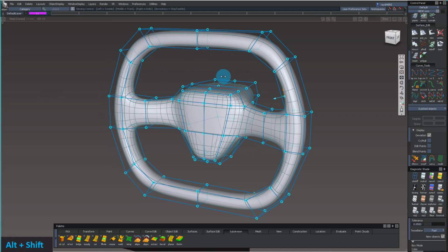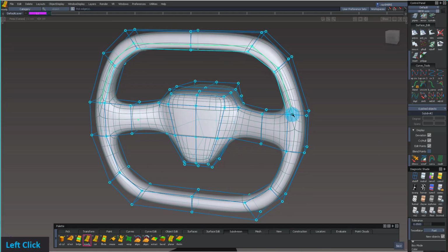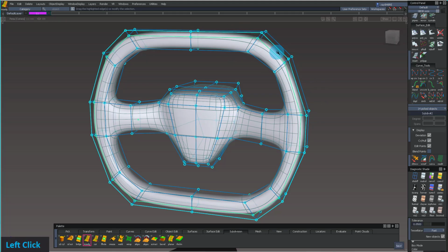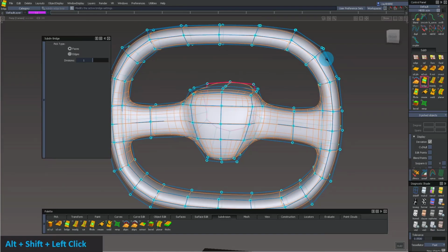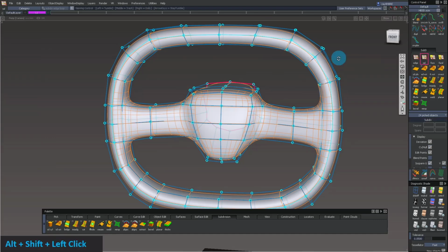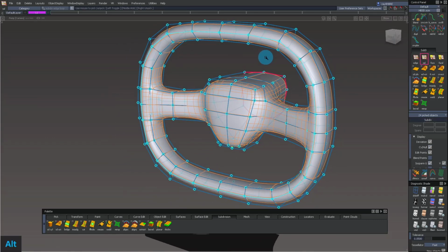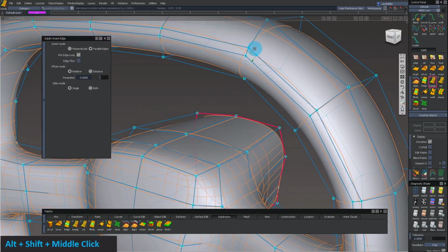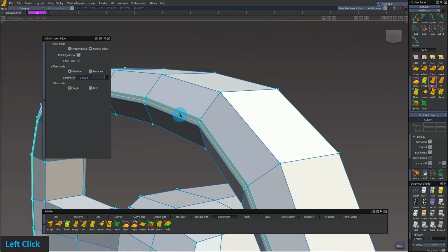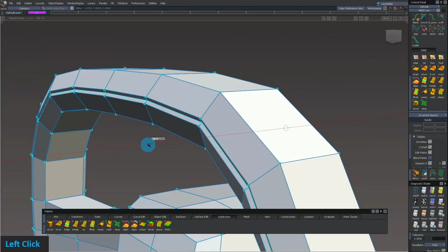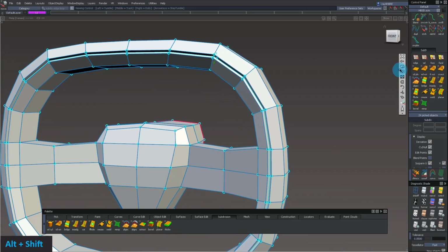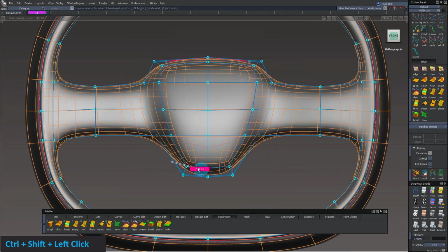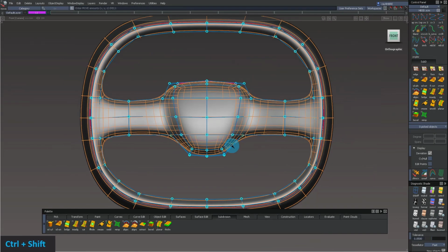If you're ever inserting and you notice that on one side it doesn't go all the way through the loop, try to touch the other side, and if it has a cleaner loop, you're more likely to get a nice clean insert. To do the first part breakup, I'm going to use my bevel tool, which is hotkeyed to Alt B in my preference set. Inside of that bevel, I'm going to insert another edge loop, then push that edge loop in so that I can get a nice little crease, and it wraps around really nicely. Since it's already selected, I'm going to use my unweld tool to separate it. After I do the same thing on the back, I can separate them and change out the materials.